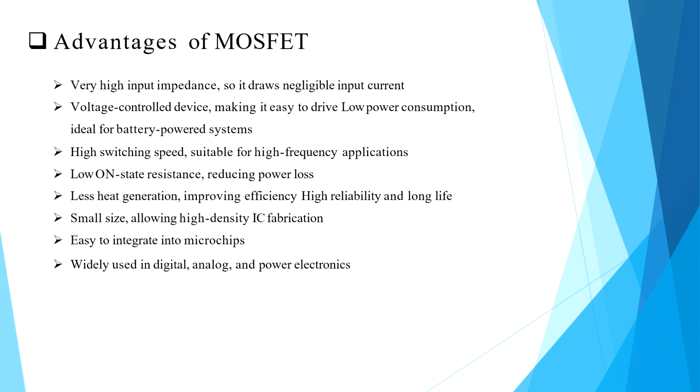It is a voltage controlled device, making it easy to drive, with low power consumption, ideal for battery powered systems. It has high switching speed, suitable for high frequency applications, low on-state resistance, reducing power loss, and less heat generation, improving efficiency. It also has high reliability and long life. Its small size allows high density IC fabrication, making it easy to integrate into microchips, and it is widely used in digital, analog, and power electronics.